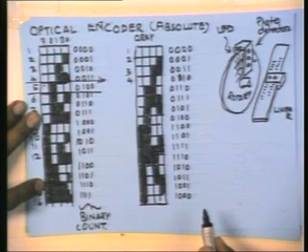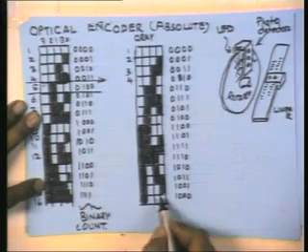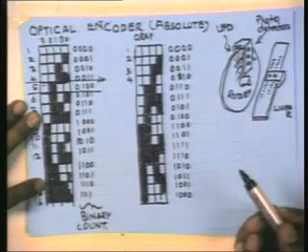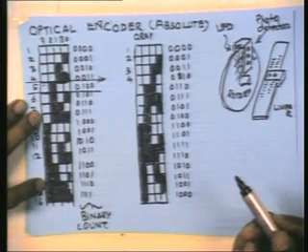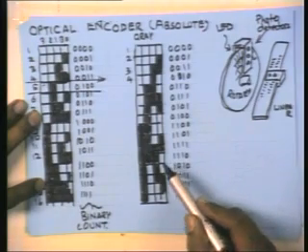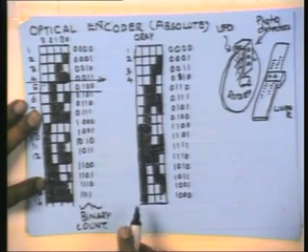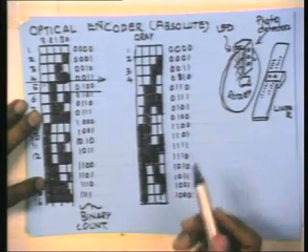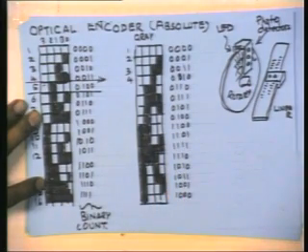So the pattern is different, but they are all unique, and therefore if I am able to correctly interpret this combination, then I can get the position correctly, and I don't have the problem of transitions, because in any transition there is only one bit changing, so either that bit would have changed or it would not have changed. The error would not be there.